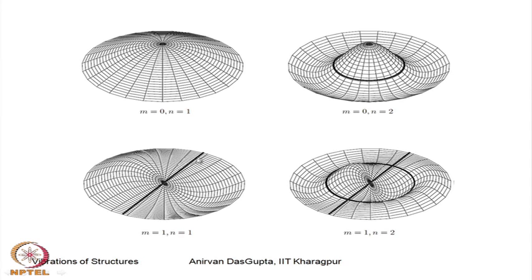So, that sets the orientation of this nodal diameter, because when m equals 1 and it is the cosine mode, it is 0 at phi equal to pi by 2. Suppose this is pi by 2, then the sine mode will be at phi equal to 0, which means the nodal diameter just gets rotated 90 degrees. So, that would be the sine mode. So, why do we have degeneracy? Now, it is very clear from this figure what we had discussed for the rectangular membrane. We had discussed the isotropy in the modal space, but now we can see this isotropy also in the physical space.